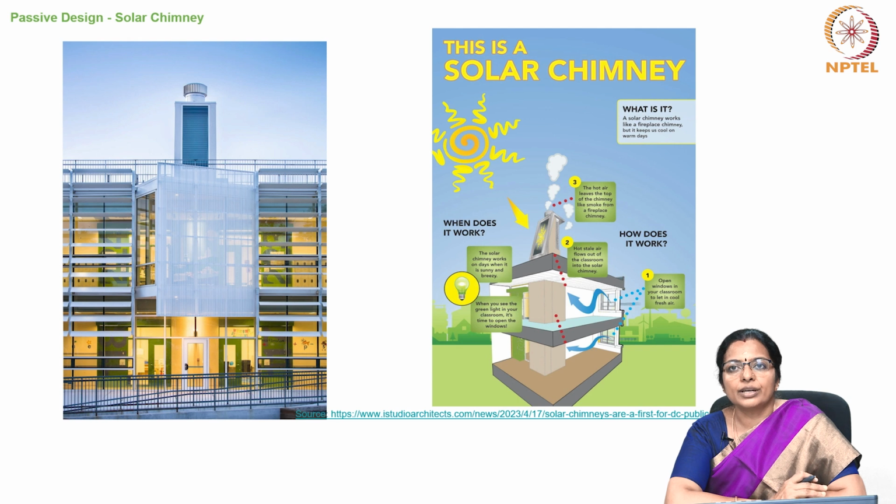This was done to reduce the energy usage and make this building more energy efficient, coupled with other passive design techniques. So, CFD models were used in the construction of the solar chimneys to produce cool fresh air without consuming any extra energy. The classroom wing solar chimney alone has resulted in about 6% energy savings.